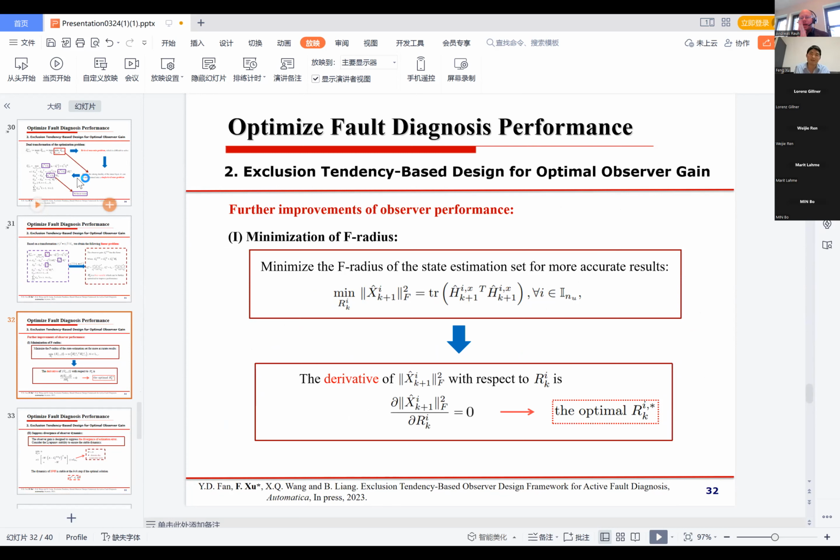Okay. Yeah. There's one thing that you didn't take into account, and I think that's interesting from a practical perspective. I think your control effort is unbounded at the moment. You could get extremely large system inputs, which are maybe not feasible in practice because you're reaching some non-modeled actuator saturations. Okay, yeah. What to do in such cases?